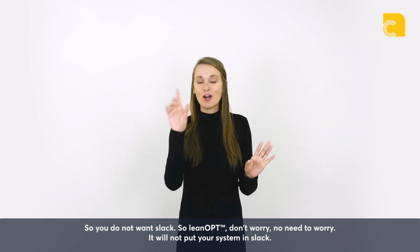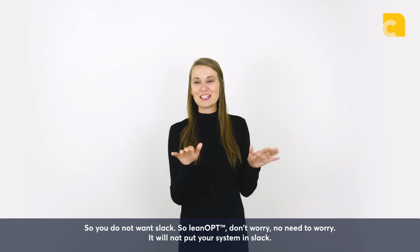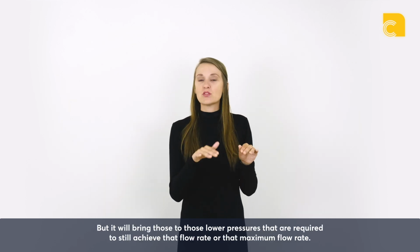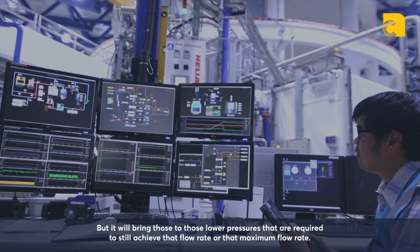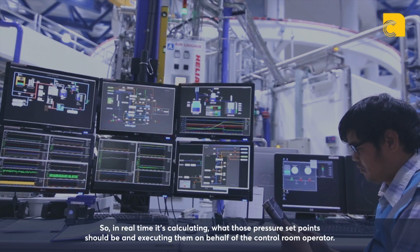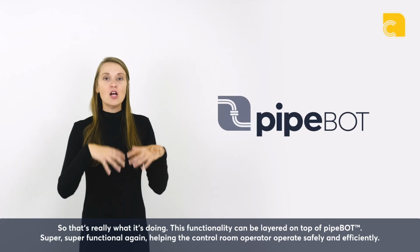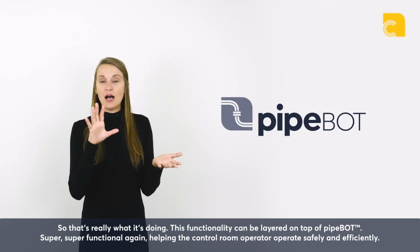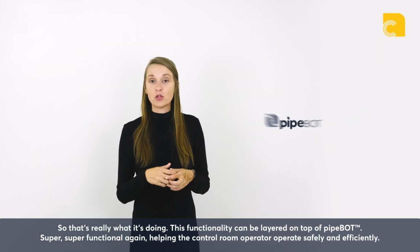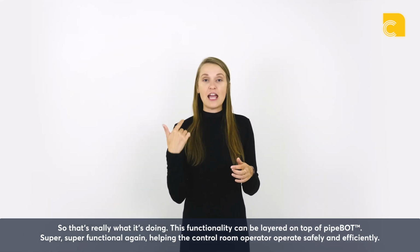So leanOPT, don't worry, no need to worry. It will not put your system in slack, but it will bring those to those lower pressures that are required to still achieve that flow rate or that maximum flow rate. So in real time, it's calculating what those pressure set points should be and executing them on behalf of the control room operator. So that's really what it's doing. This functionality can be layered on top of PipeBot. Super, super functional, again, helping the control room operator operate safely and efficiently.